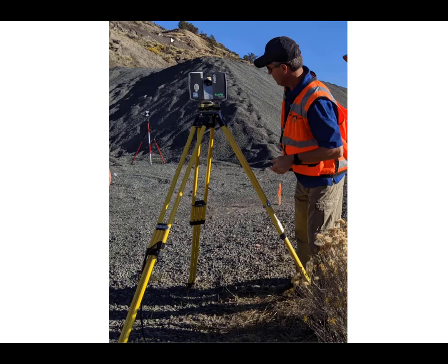So we went up to the terrace above, which has 2 more stockpiles on it, to look down and capture the top of the stockpile. The Faro scanner wouldn't look down steep enough to capture points. So we used the reflectorless total station to get points on top of the stockpile. Stockpile is pretty much flat on top, so we didn't need a lot of points to get an accurate surface model for the top of the stockpile.